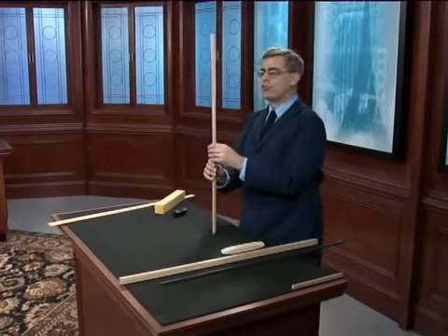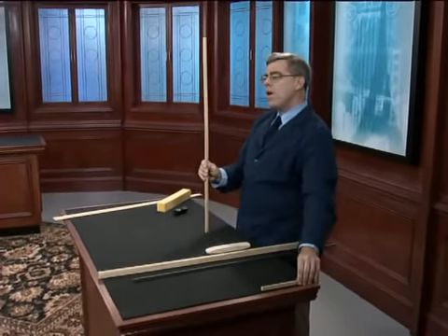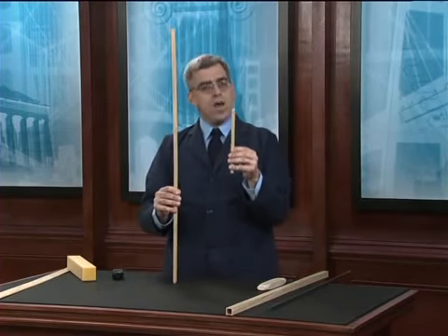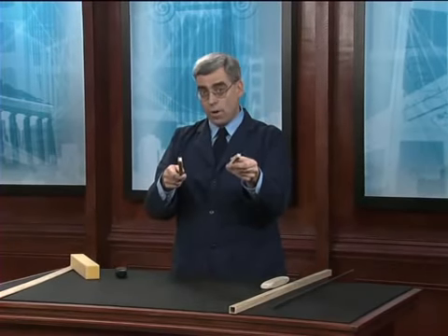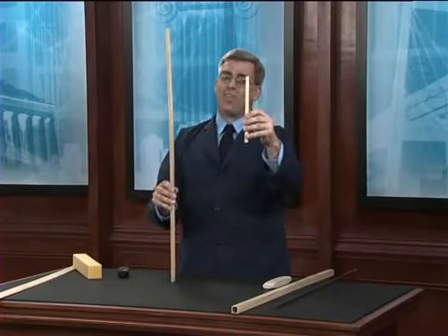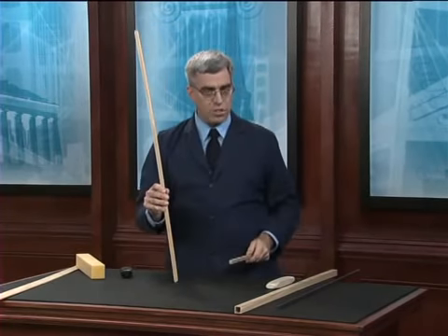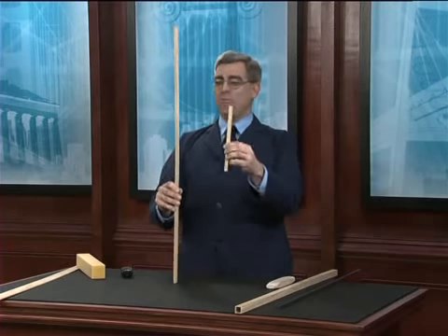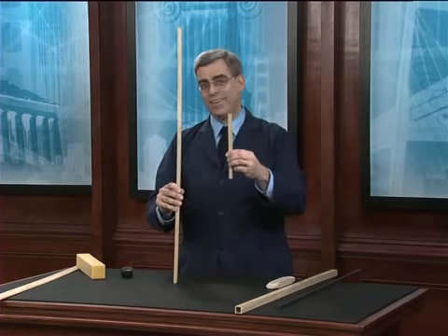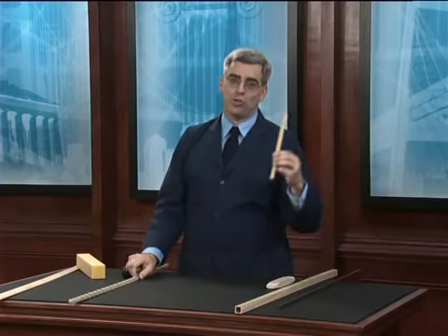That's the 3/8 inch square member. But this time, I'm going to compare it against another wooden column with exactly the same cross-section. Both of them are square, same size. But now, obviously, this one is significantly shorter. It's only 6 inches long. Predictions, please. Which one of these two will be stronger in buckling? What do you think? Well, clearly it's going to be the shorter one.